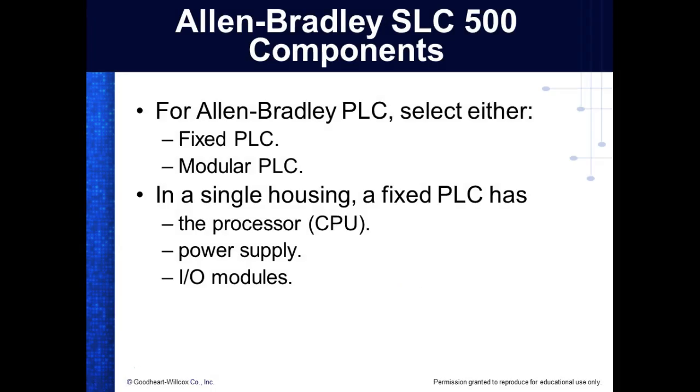So here in the Allen Bradley line, and this is true of the major manufacturers, they make two types. They make what we call a fixed PLC, and then they make what we call a modular PLC. And I think we talked about this last class, right? So what's the advantage of a fixed PLC? Price. Yeah, it's a lot cheaper. And what's the advantage of a modular PLC? Well, you get what you want, right? You can specify and buy what you want. And usually modular PLCs are very expandable, and they're very flexible, right? You understand?